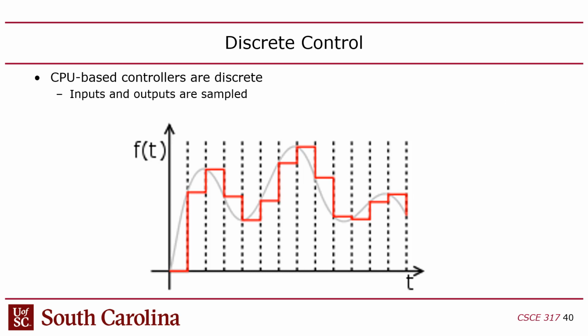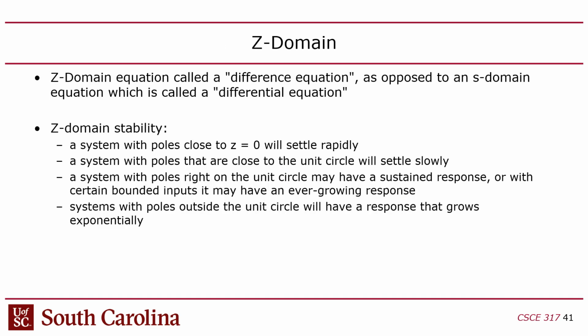Okay, so what ends up happening is that in a discrete controller, you have this continuous signal, but because everything happens at discrete points, the computer updates at discrete times, you end up digitizing, you create like a Nintendo type step pattern that follows the continuous signal, right? Okay, so basically the idea here is that you start with a time domain, but it's not continuous time domain, it's discrete time domain. So you got the brackets in there, bracket T, bracket K, not parenthesis.